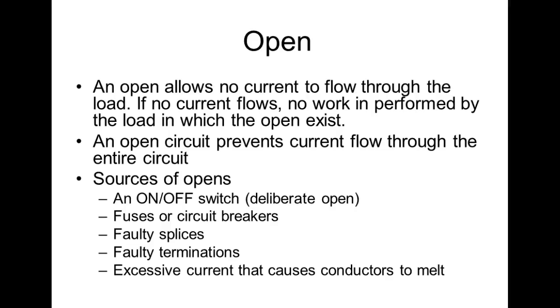Well, when the students picked it up and were moving it over, they didn't disconnect the cable. And what happened? It was a little old tiny thing. Just jerked that thing right apart. So now we had an open, right, that we had to repair. By doing what? By splicing, right? So sometimes we accidentally put opens in by putting too much stress on the conductor.